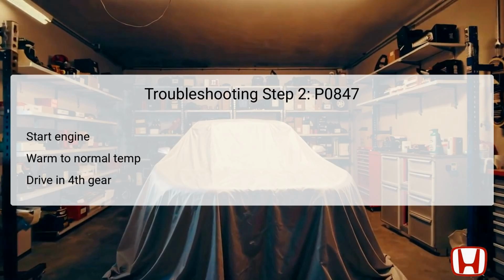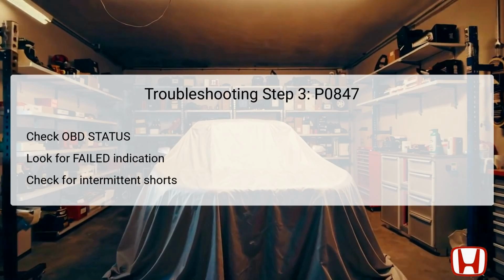The data collected throughout this step provides meaningful insights into the status of the switch and its associated electrical connections, assisting technicians in determining the switch's reliability during various operating scenarios. Upon concluding the drive, the next crucial step is to monitor the OBD, onboard diagnostics, status for the P0847 code within the DTC's menu using the HDS.